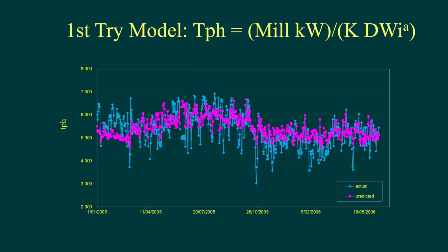If there is an ore change today in our mine, we might not see that ore change coming through to our grinding circuit for 1 day, 2 days, even longer. So the mine plan would say, for one of these blue data points, there has been a change in ore on this particular day, but the process plant won't see that change until several days later. And if you don't recognize that lag, you sometimes find it very difficult to match up the peaks and the troughs because of that time lag.